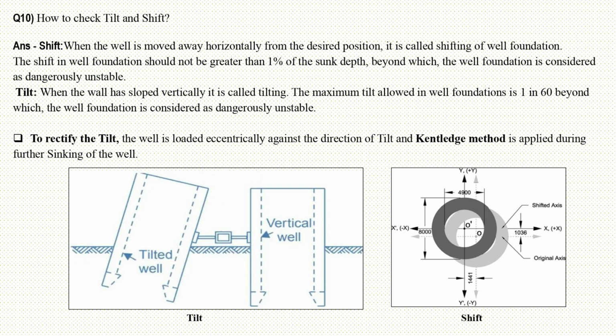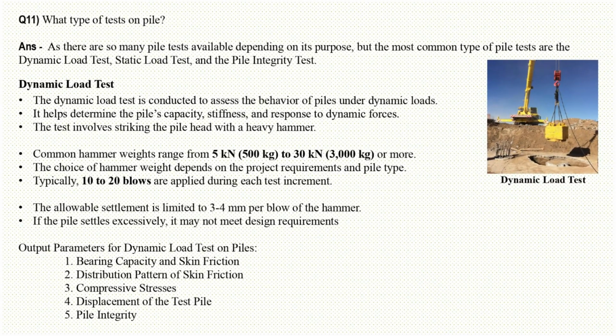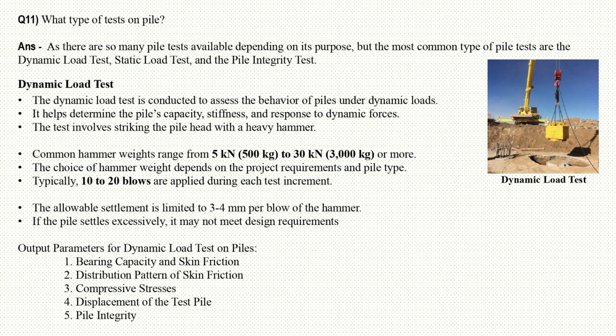Question 11. What type of tests on pile? Answer: as there are so many pile tests available depending on its purpose, but the most common types of pile tests are the dynamic load test, static load test, and the pile integrity test.